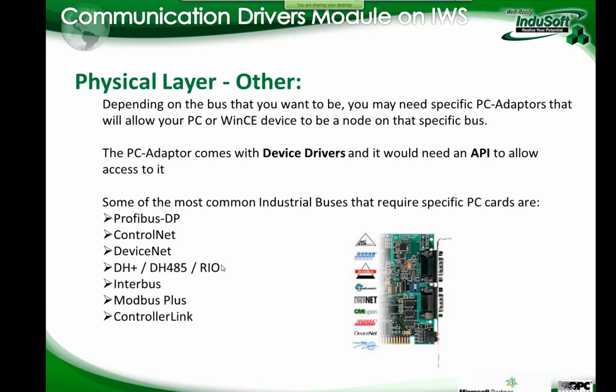You're going to put in their SST card, for example, or SA85. Those are not things that you have on any PC, so you're going to need to connect either a USB port or a PCI card. It's different hardware. You're going to need to install the device driver for it on the operating system, configure the device driver, and test that communication using the built-in tools that come with those boards.